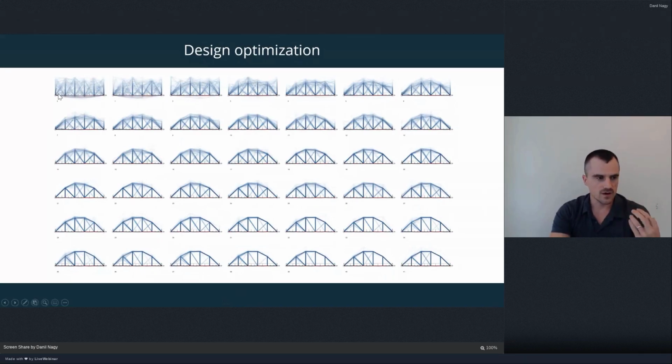So a genetic algorithm works through generations. It actually optimizes based on looking at sets of designs in order. And here's the first generation. It starts by looking at a certain number of random designs. You can see there's a huge variation in these designs and what they look like. But then over time, as it keeps generating designs and learning more and more about which ones perform better in those evaluation metrics, you can see it starts to narrow in on the best design and ends up converging on a design that we would intuitively think would make a good bridge. It's got that curved catenary shape.